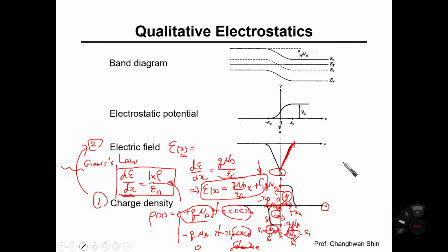How do we get it? Yes, when X is Xn, the electric field intensity must be 0, at this point. Because beyond Xn there is no charge, and no charge means the electric field intensity must be constant, here 0. But in the area slightly below Xn, the electric field intensity is negative.